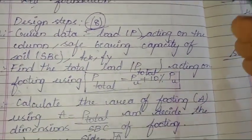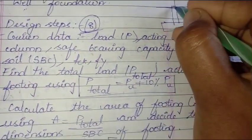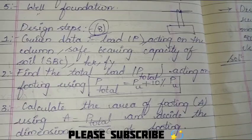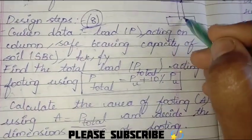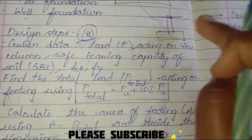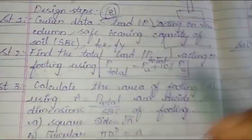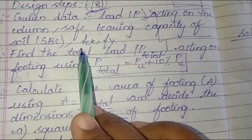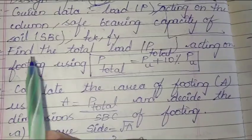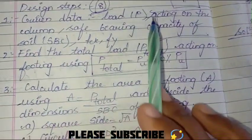Okay, given data: load acting on the column. Whatever the load that is acting on the column, see, this is the footing, but we have some column over here and the load is acting on this column. Bearing capacity of the soil. Whenever we talk about the foundation, we are talking about the column, that is the superstructure present over this, and also the soil to which it has to transfer the load. First of all we will be given fck and fy, that is the yield strength of the steel and the characteristic compressive strength of concrete. So the first step is writing all the given data.